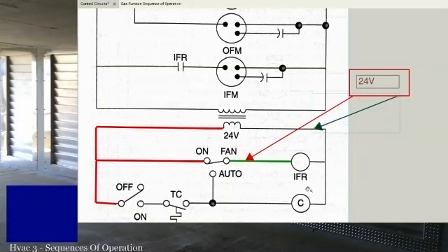If you're checking the ground, I've seen guys scratch their heads for a long time because, on high voltage especially, you're checking hot to ground instead of hot to neutral. You can have 120 volts hot to ground and 90 volts hot to neutral. You can have 24 volts hot to ground on a transformer and then 12 volts hot to common. And then you can have 48 volts hot to common if you got two transformers in there and they're bucking or something. So if you're checking to ground, hopefully you're really proficient at what you're doing, because a lot of times it can get you in trouble.